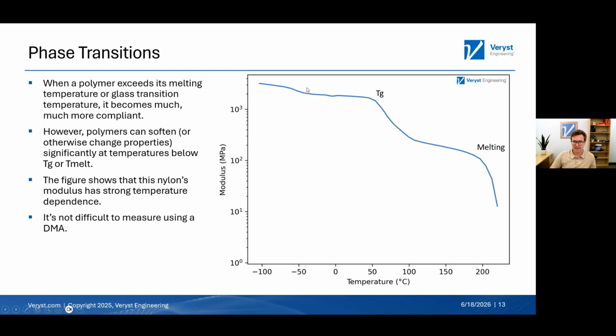So if we look at this curve, between very low temperatures and about 50 degrees Celsius, you do have a pretty significant dependence of the modulus on temperature, but it's much higher above the glass transition temperature. Once we get those rubbery domains, they're essentially more temperature dependent. So even if this is the state you want your material to be in, it's going to be more sensitive to fluctuations or changes in the temperature.